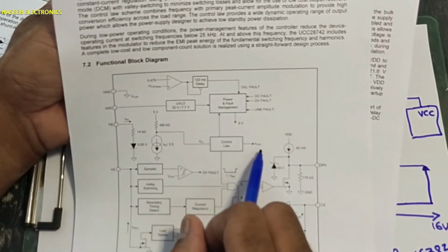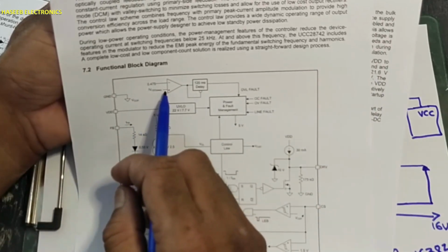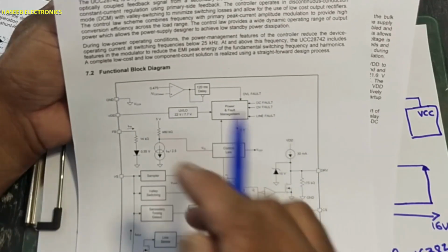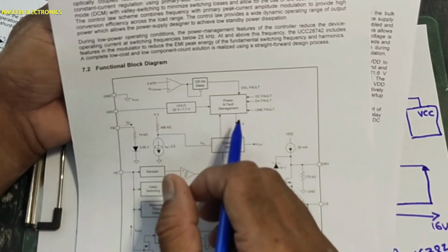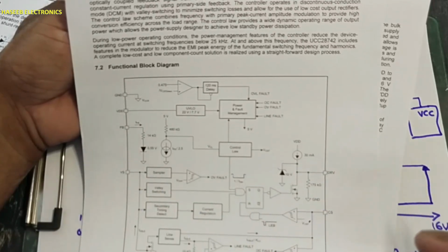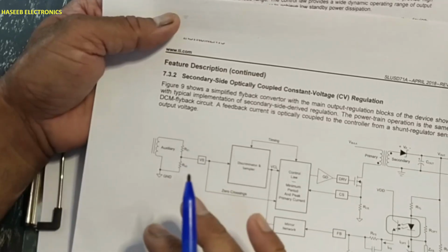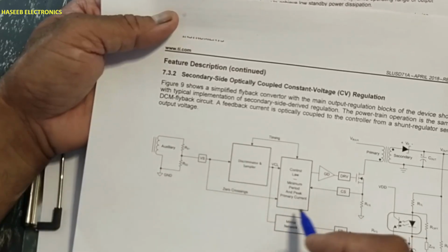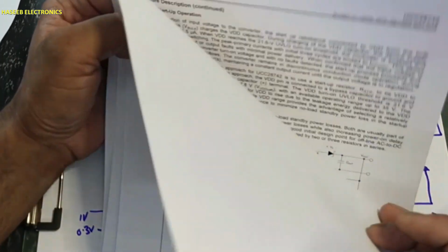And if the VCST signal is above the limit that is set here, at that time it will turn off the circuit. When it turns off the circuit, it will provide a 120 millisecond delay to reset the fault condition. If feedback is missing, over current, over voltage, or if the VDD voltage is above the limit, above the zero crossing level, at that time it will generate a fault, that there is an overloading condition in the output.